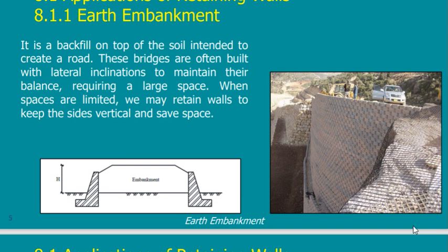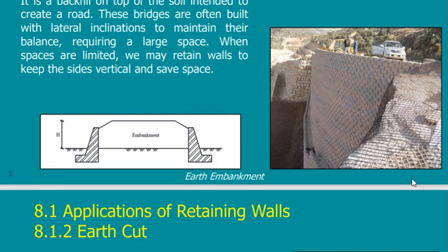So in this case, I will cover the slope with something. This something may be a wire mesh, a geotextile mesh, or anything that would cover the slope to keep the rocks in place, to avoid pieces of rock going loose with time and falling down.